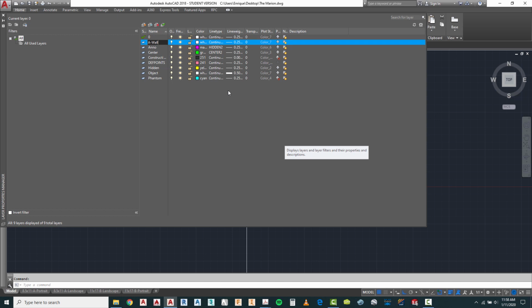In this case, the major group is going to be called walls. It needs to be only 4 characters wide. In our case, we are going to capitalize just the W, and the rest is lowercase. Then after we have our discipline and our major group, we're going to have what we call our first minor group, and we're going to call this one EXTR, 4 characters again, and that represents the exterior walls that we're going to do.